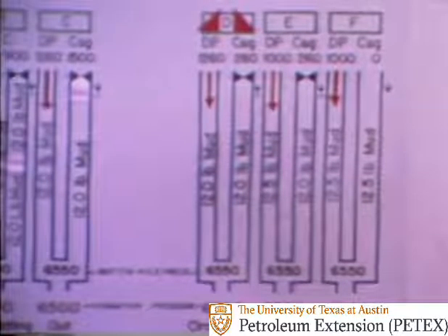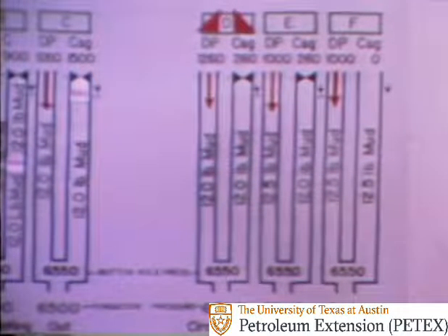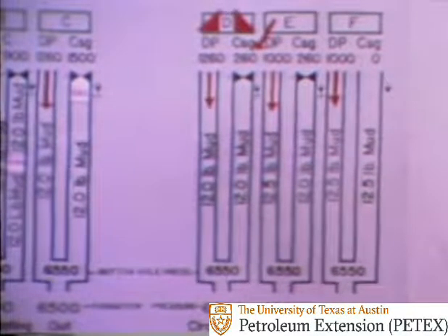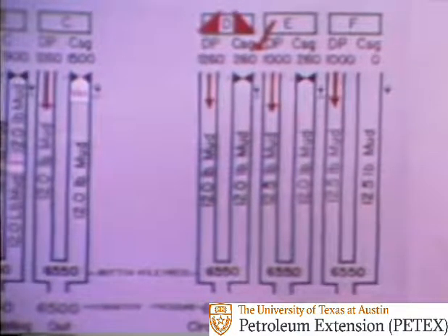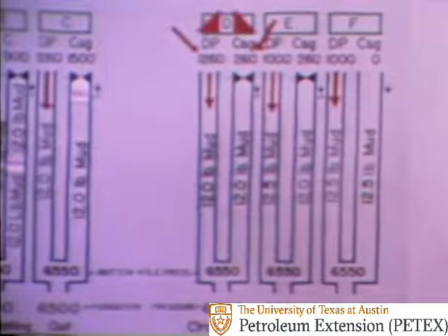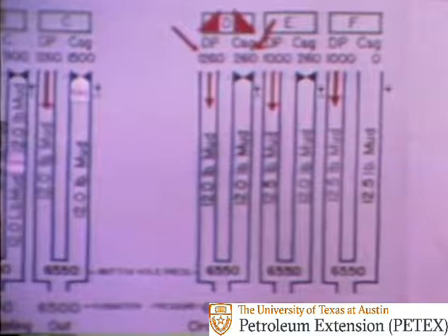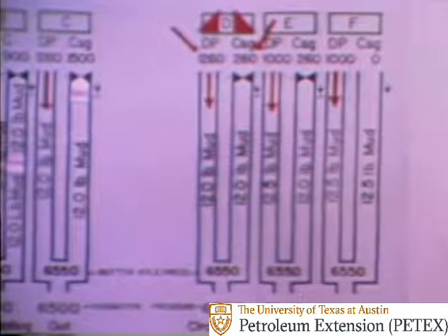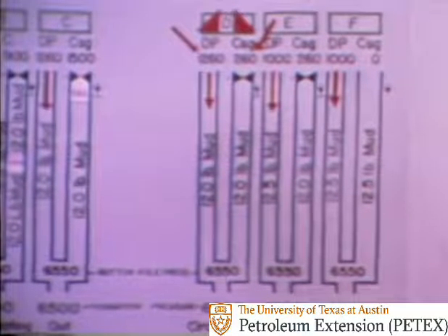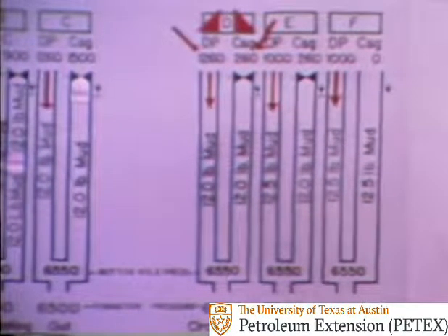When all of the gas is circulated out, as at D, the casing pressure will drop to 260 psi. The pressure needed to continue to maintain the 1,260 psi circulating pressure on the drill pipe. If the need arises, the pumping can be stopped and the choke closed, in which case the drill pipe and casing pressure should be the same, 260 psi.